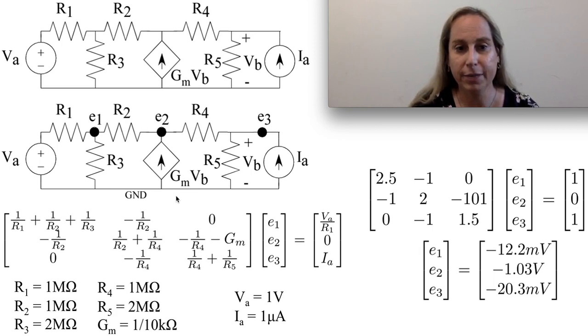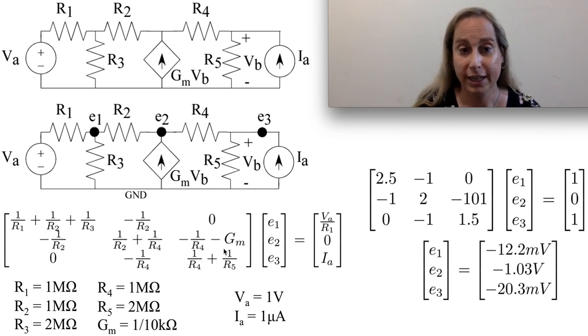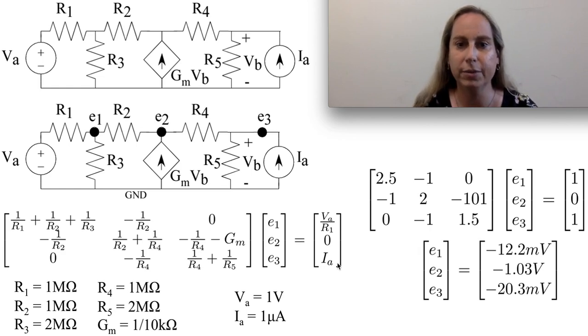So then the question becomes, how do I begin to look at the matrix that I might create for the solution? In a nodal case, remember, it's going to be a matrix of conductances times a vector of voltages equals a vector of currents. So it's basically a form of Ohm's law, knowing that I'm dealing with conductance and voltage, and the conductance and voltage give you a current. Okay, so how do I create these?